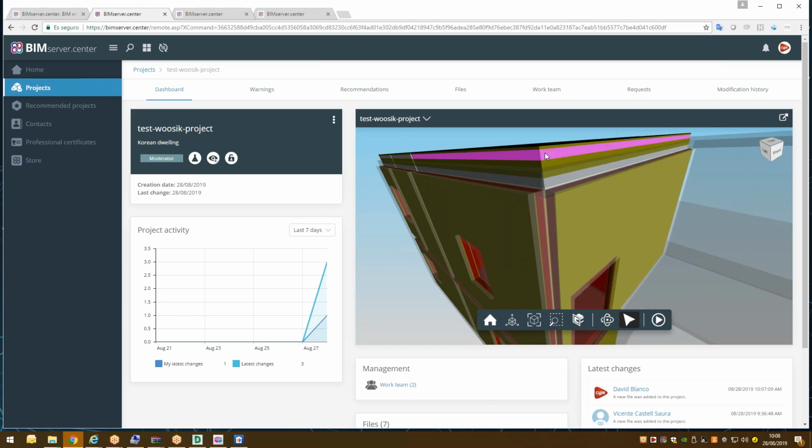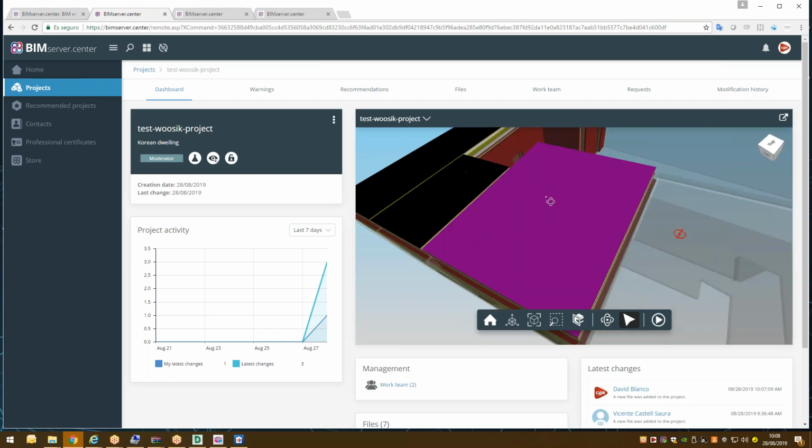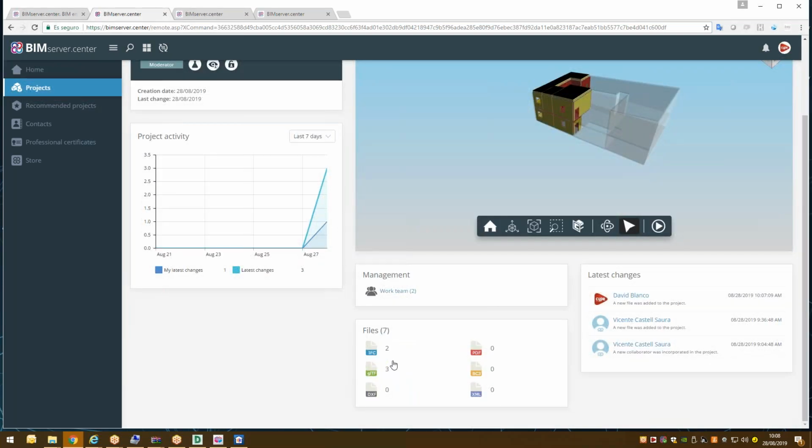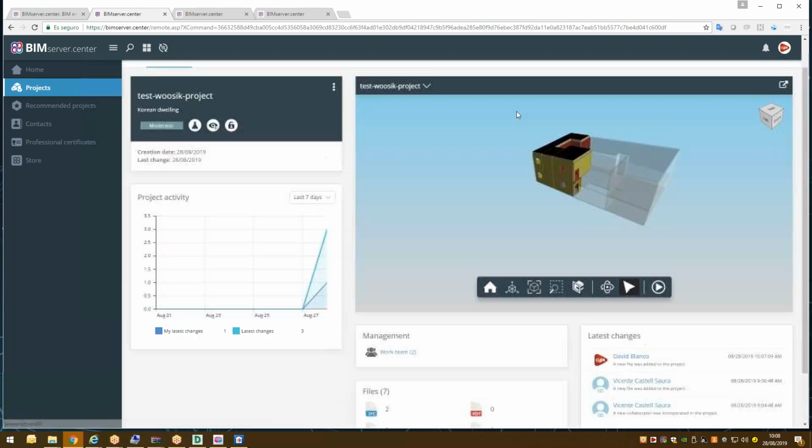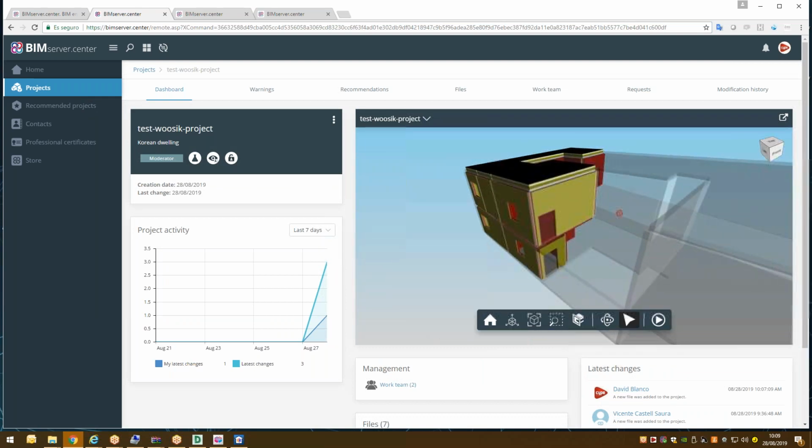You see, this is very interesting for architects and also for engineers, but obviously for the BIM manager, the information of each layer and the U value of the thermal resistance according to each layer. Okay, this is quite nice. And this is all exported and contained only in the BIM platform. You see, the information is increasing. We are consolidating the BIM model step by step and improving it, introducing the information for each calculation. In this phase, we have provided the thermal loads analysis. This is the thermal model in layers or by elements that you can consult.